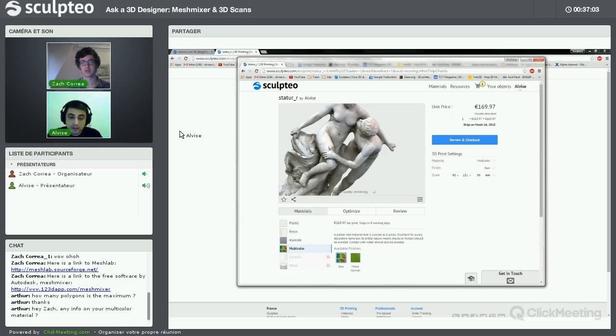The tool is completely automatic, and it's related to the material that you choose. So if you change material, even if you rescale the object, the thickening tool will automatically update and modify the geometry in that area.